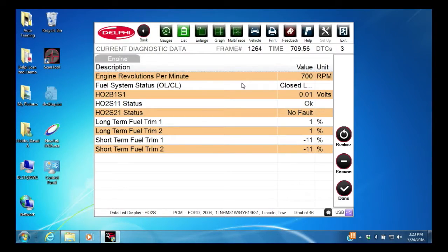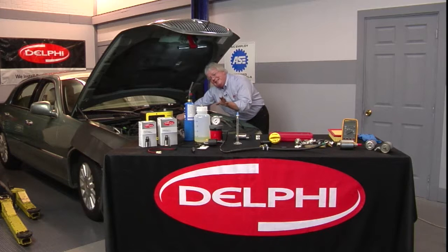above 0.6. So now I've got some lean going on to compensate for the rich, and we are compensating. O2 goes to the basement, goes to 0, very low, not switching much because it's very lean, big vacuum leak. With a mass airflow, we can do this. Speed density just speeds the engine up because it says, hey, we have less vacuum, I'll add more fuel. In this case, this is air the mass airflow doesn't know about.